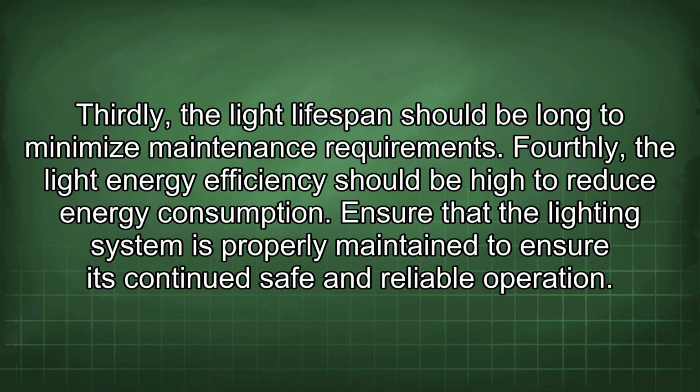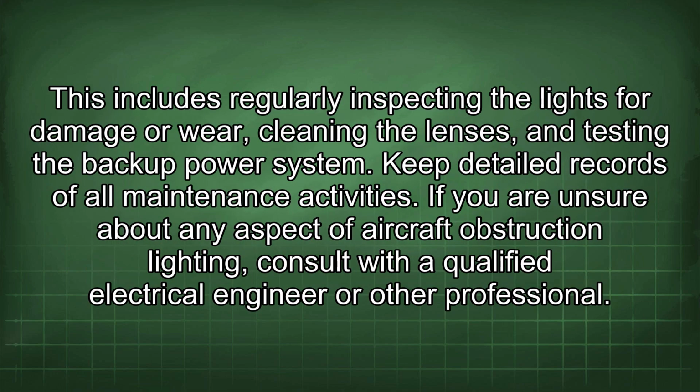Ensure that the lighting system is properly maintained to ensure its continued safe and reliable operation. This includes regularly inspecting the lights for damage or wear, cleaning the lenses, and testing the backup power system. Keep detailed records of all maintenance activities.